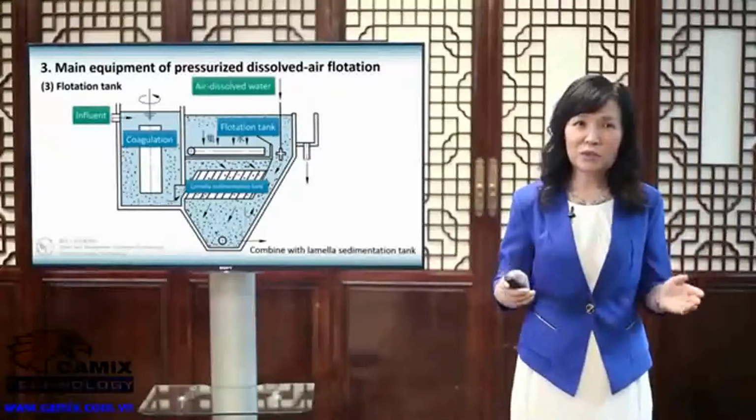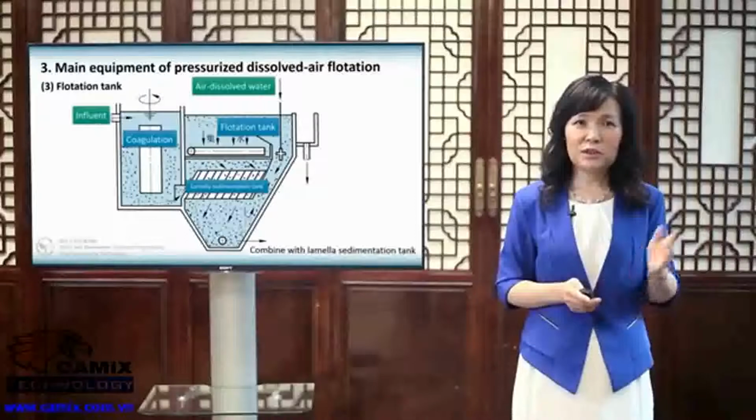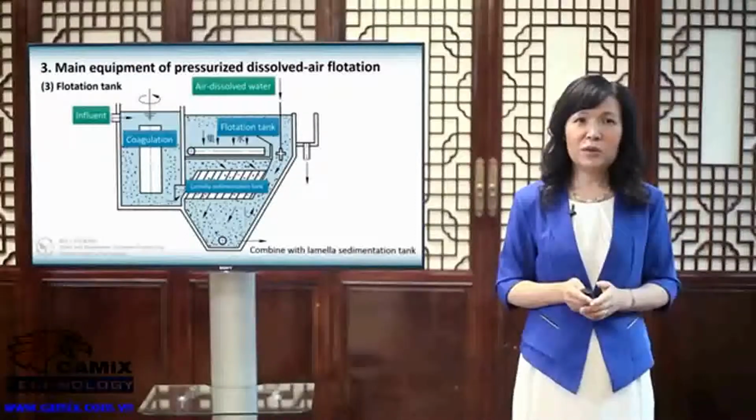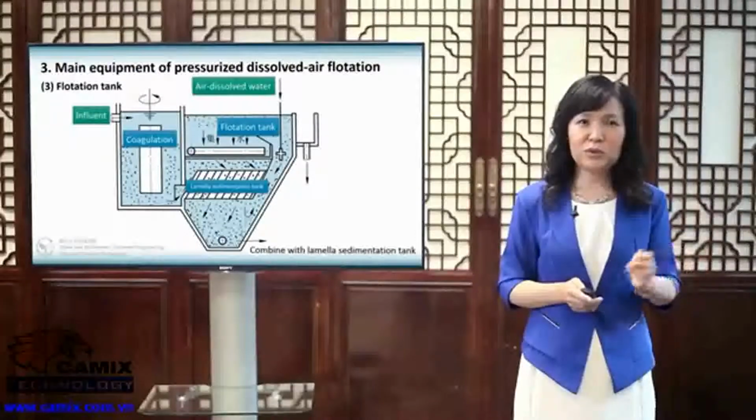Then it flows into the flotation tank on the top and is mixed with air dissolved water to further remove the fine impurities through flotation. Whether the particle is easy to settle or not, it can be removed efficiently by the combination of the two processes.